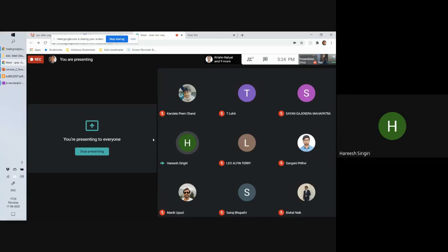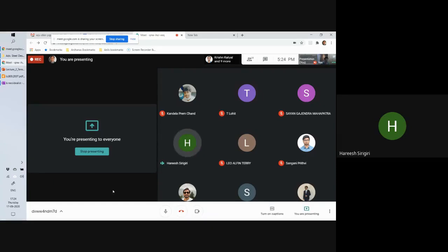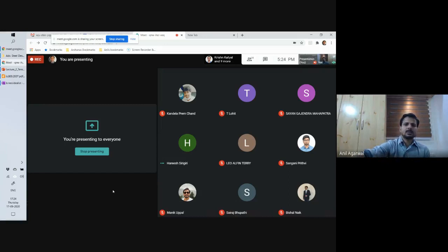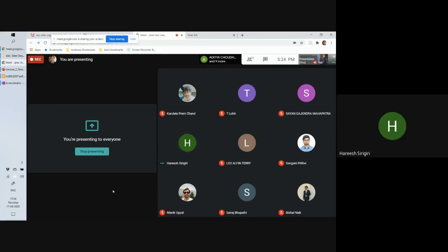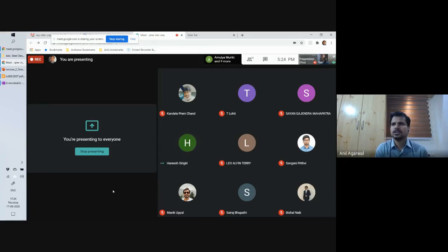Sir, can we say that slenderness ratio is a stability parameter, sir? Yes, slenderness primarily governs the stability behavior of the structure or the member. Yes, that is true. Because where do you get L by r? The concept of r, or L by r, comes from your pi square EI by L square, right? The relationship between L and I, or L square divided by I, is primarily coming from your Euler buckling equation.